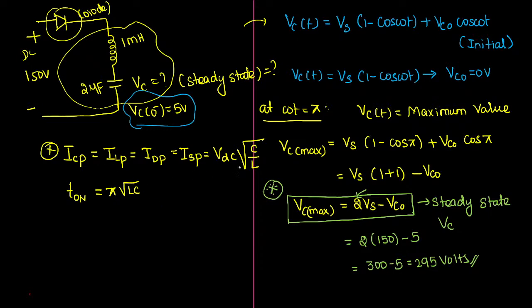Sir, and one more thing. Here I haven't covered the initial voltage. This is when VC not equal to 0 volt. Suppose VC not is not equal to 0, then what should I do, sir? Then the same capacitor current can be written as supply voltage minus initial voltage, you should subtract it, that's all, into, as usual, the same formula, square root of C by L. Undoubtedly this will be the resultant answer.